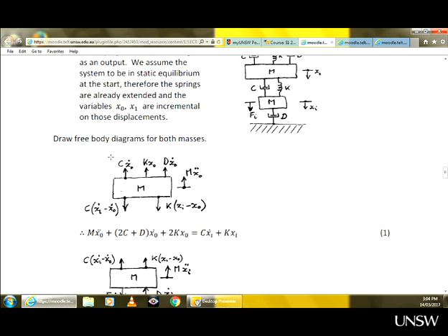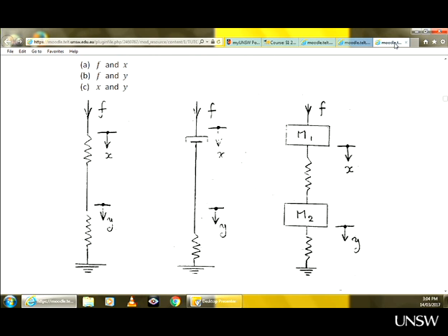This torque is (theta P minus theta O) times K2, obviously, minus C2 theta O dot. That equals the inertia. And that is really similar to these problems here. Here you have a constant force. Here you don't have a constant force. This force here is not the same as the force here because of inertia.